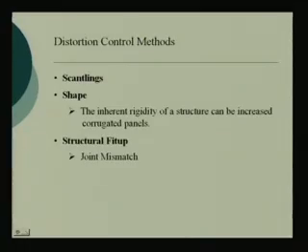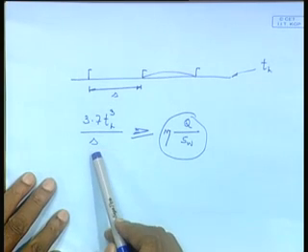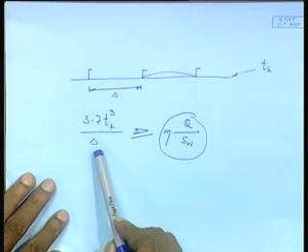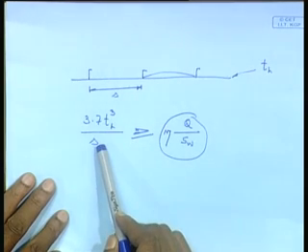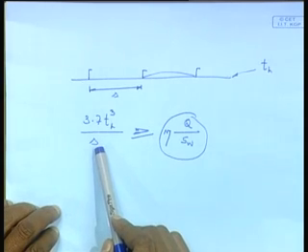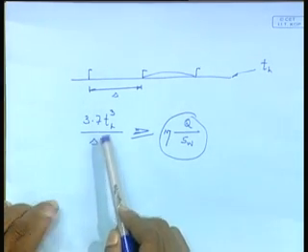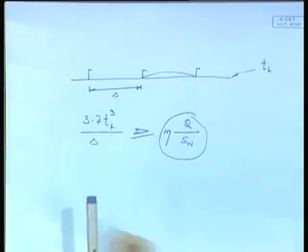Frame spacing, say 800 millimeter. There we had been talking about this S. If I use higher frame spacing, it becomes more prone to buckling for the same thickness. Lesser frame spacing, it is less prone to buckling. But lesser frame spacing, on the other hand, may increase the weight. So, all these aspects are to be seen. That means, scantlings one will also have to take a look at.